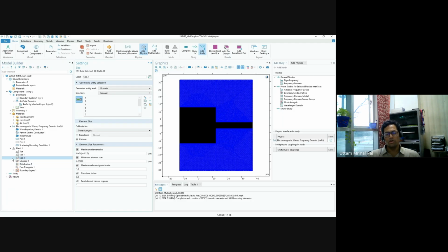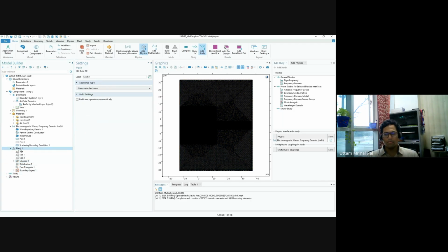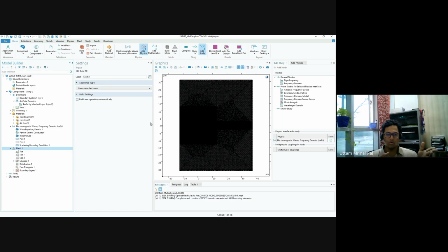You can also try to squeeze this from both sides, because having such a long core for the single mode, I don't know if there are no propagation losses. Are there any losses in your domain? Is it a lossy domain? No, sir. Currently there is no loss. Then it doesn't make sense to have such a 10 micrometer, 20 micrometer long single mode fiber, and almost 20, 30 meter long multi-mode fiber. You can have just 1 micrometer. Do you understand?